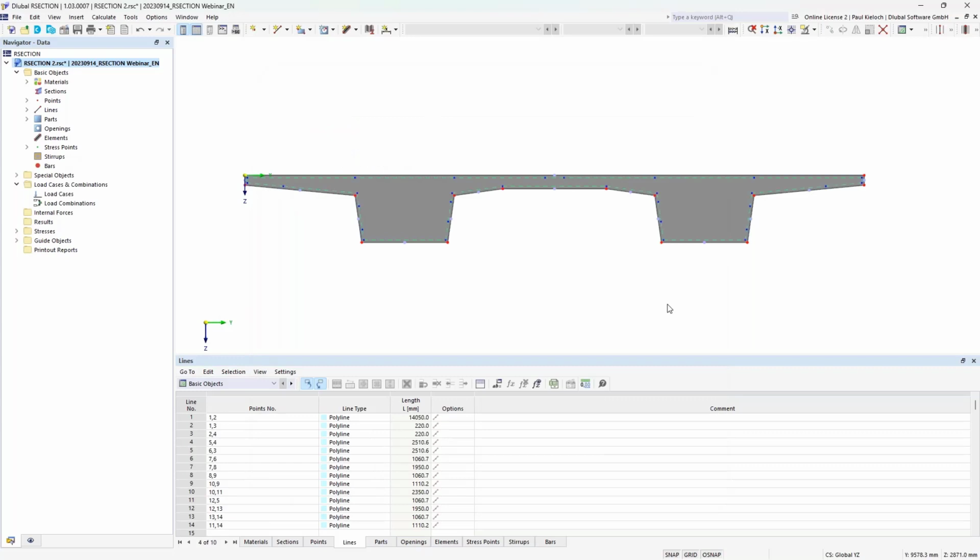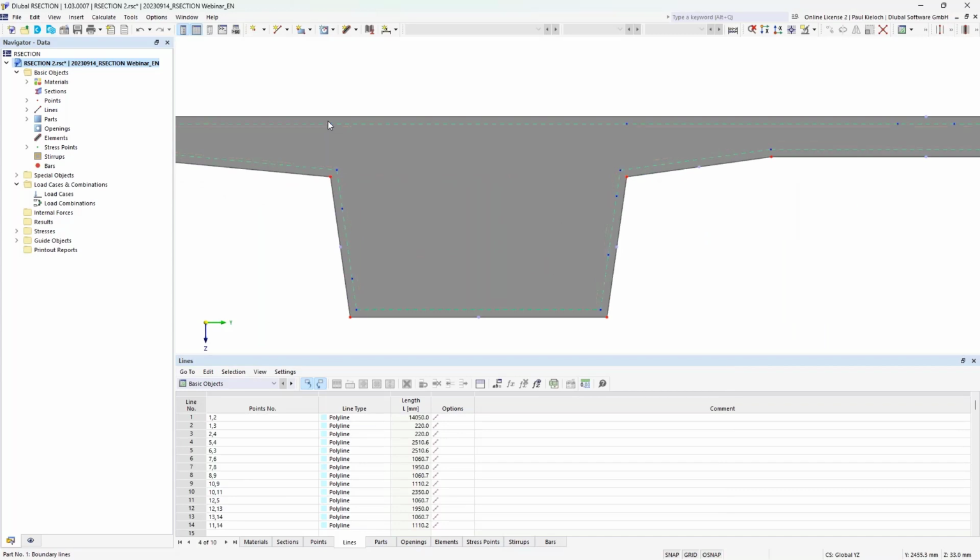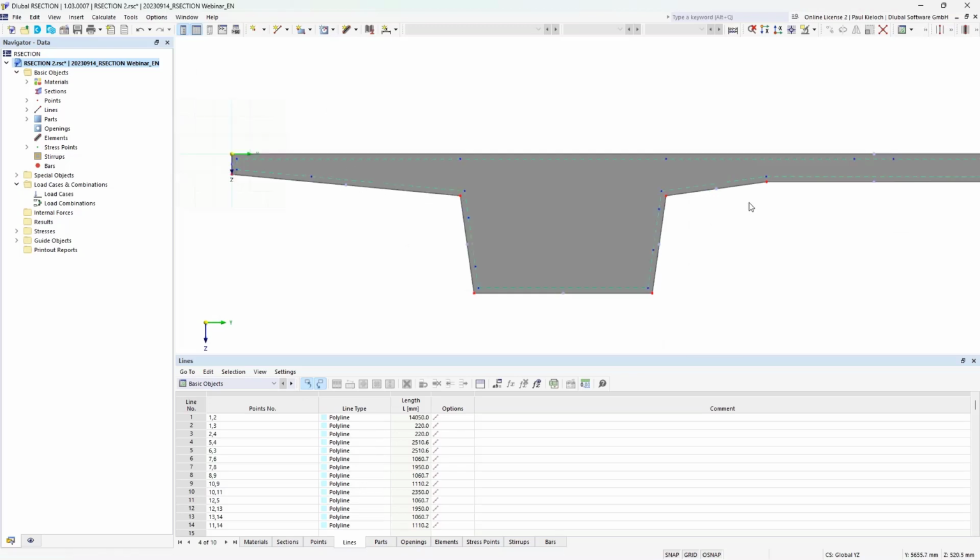And then we will see again our lines with the concrete covering, and again our blue dots here, our nodes, that are helpful for generation of these stirrups. So this is always just an extended line from, for example, this line. If we would extend this, then we would get this node and so on. Okay, that was the second way with import of DXF file.